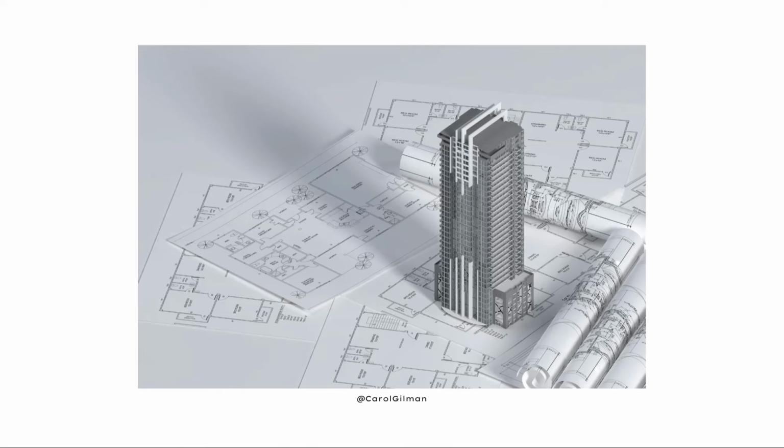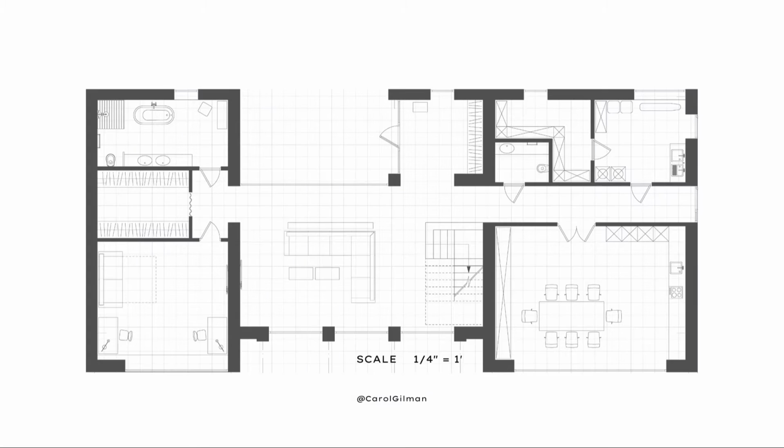So an architect, maybe they are working on a commercial building. Lots of times commercial buildings are drawn to the scale of 1/8 of an inch equals 1 foot. That means when they are drawing this out on the computer program or on a piece of paper, they are drafting everything out where every 1/8 of an inch equals 1 foot, because commercial buildings in general are usually much larger than a home, where we would just use 1/4 inch equals 1 foot.